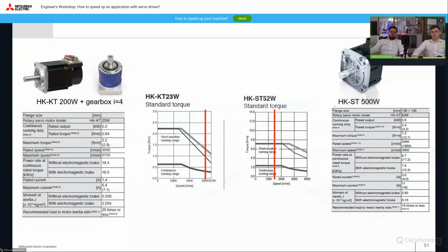So even though in theory the 500 watt middle inertia motor is slower, in a real application at similar cost it will give us the possibility of increasing the maximum speed, and it will remove a gearbox which also puts up some resistance and wears out. It's possible, provided of course that we will be able to fit a motor with a much larger flange, and the angular acceleration of the middle inertia motors will be sufficient to meet our requirements.